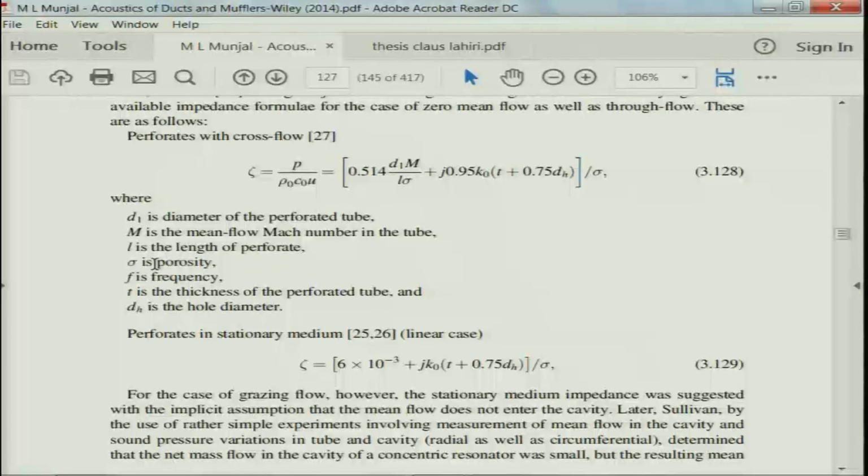At the same time, acoustically the performance will be very similar to that of an extended inlet and outlet muffler. So, it would not affect much acoustically, but it definitely has a very good influence on reducing or eliminating the separation noise that would otherwise occur.